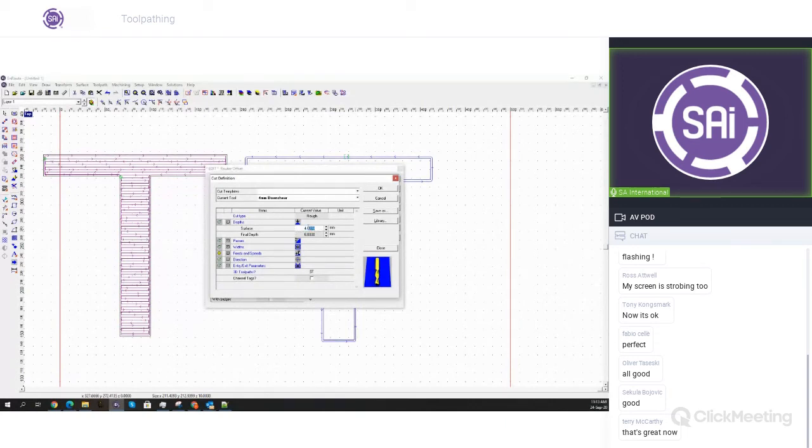So if you want to tell EnRoute you don't have to route that first 4mm anymore, you can just set the surface to 4 and then the final depth to 6, coming to a total of 10 to route through it.